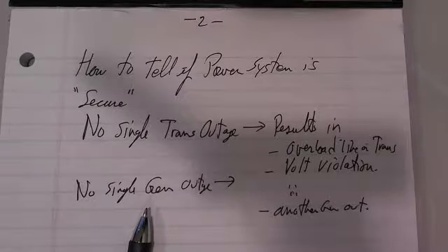And if you have too few generators, or the ones that are operating are right up near their max, and you lose one, maybe you lose a 700 megawatt generator, where is that 700 megawatts going to come from? Generally it can come over connections to other utilities, assuming that they have a lot of extra capacity, but it should come from your own eventually. And if you don't have enough extra capacity, called spinning reserve, then the frequency is going to start to drop.